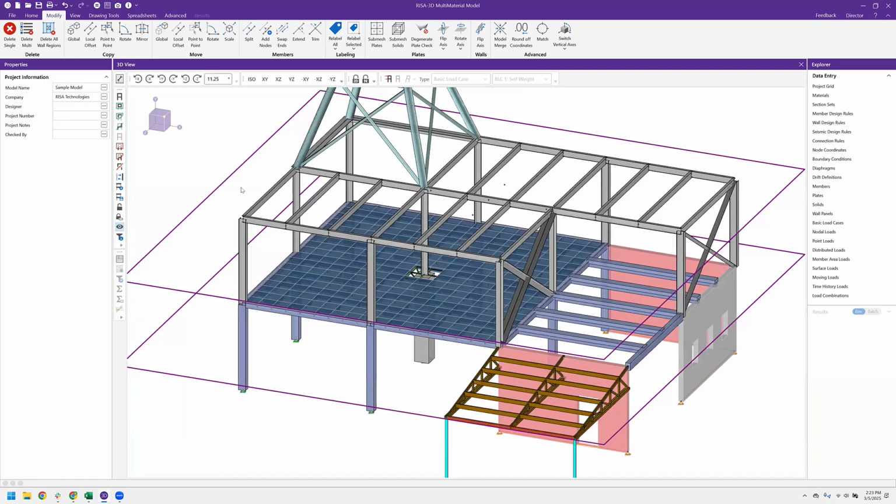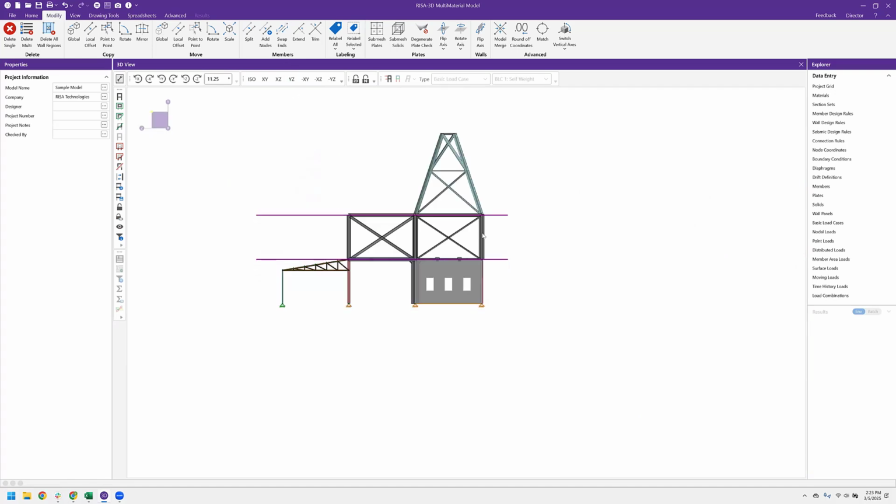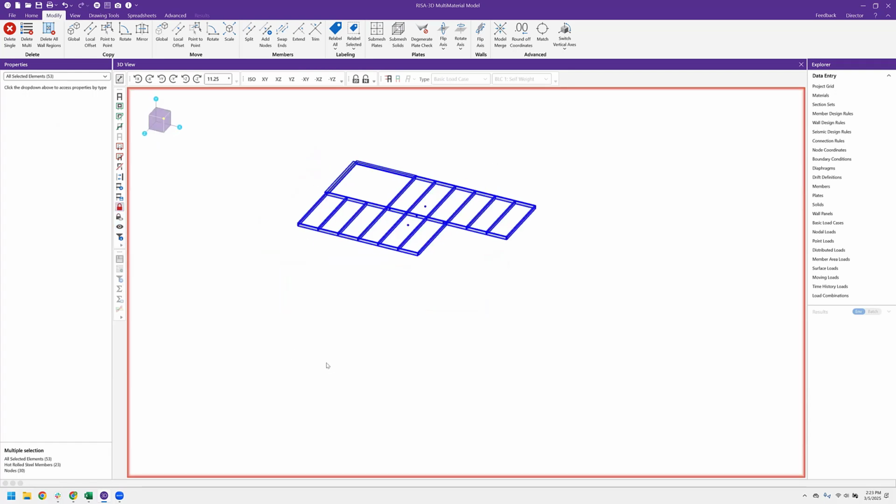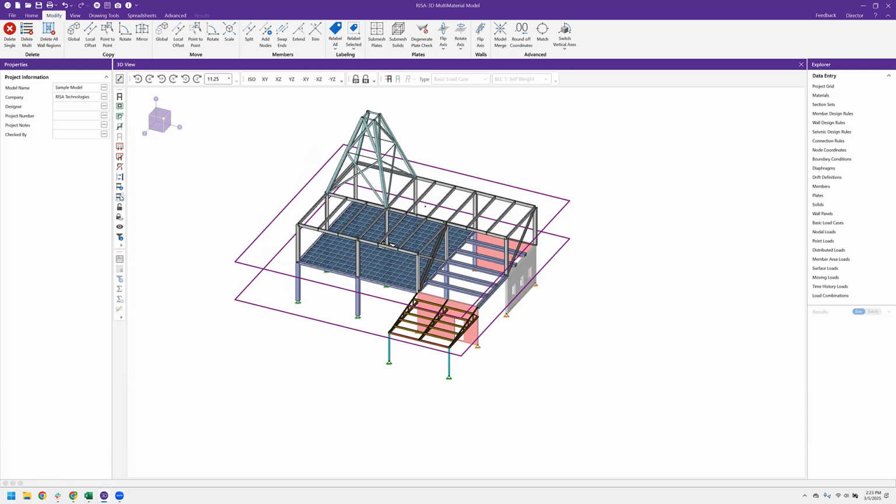If we select the elements that we want to select here, I could use our viewer mode, or I could use our lock to turn those elements off completely to see what's available there. I could also use other selection tools like opening up save selections. If I have a save selection here, I can create those selections so I can go back to them time and time again.